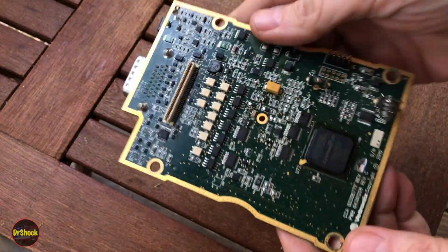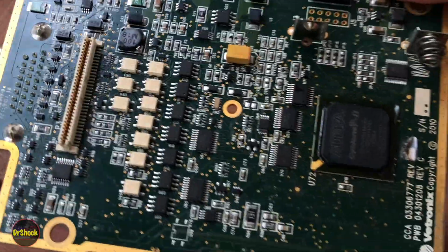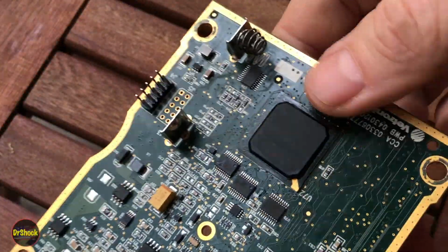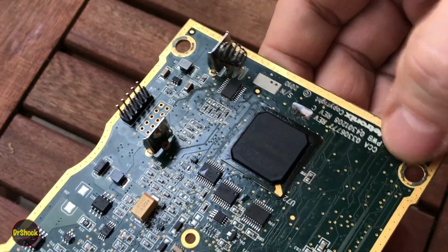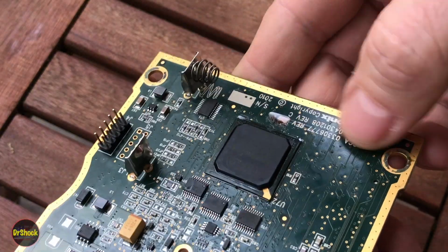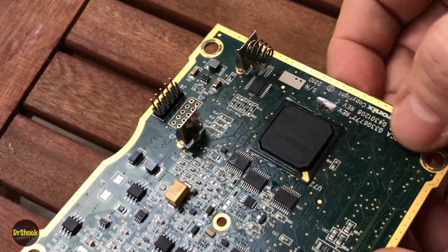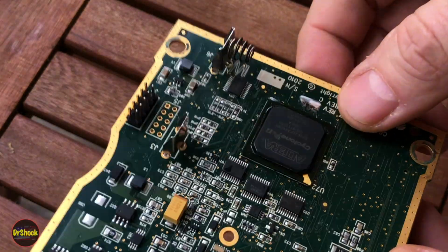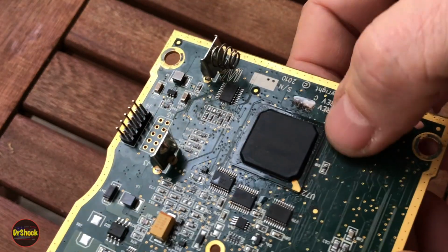All right, guys, so what went wrong here? Why did this repair fail? Well, I can tell you why, and it wasn't the rework profile. If you look at the previous clip, you can see some brown fluid in the right-hand margin of what we were filming, because we had this kind of orientation of the camera during the previous clip. And at the time, I thought that might just be some flux runoff, but it actually turns out it was underfill. And that underfill obviously had a different thermal profile.